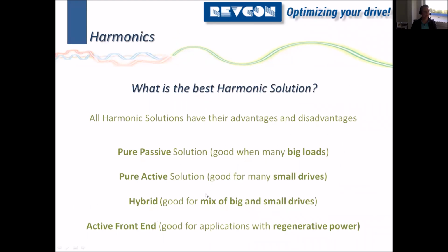Okay, so what is the best harmonic solution? All harmonic solutions have their advantages and disadvantages. Pure passive solutions are good when you have many big loads. Pure active solutions are good when you have many, many small drives. So there are situations where active solutions can be the superior choice.